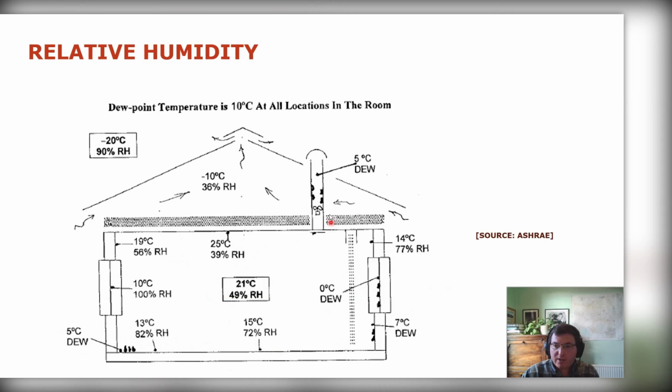Another interesting point shown here is that, let's say we have an extractor fan that takes this warm, moist air and pumps it out. Now, if inside this duct itself, it cools down because the loft that it goes through is cold, and the walls of it lower down to say 5 degrees C, again, it's a dew point, and at that point we start to get condensation inside the duct, and then we get water and maybe corrosion and a growth of algae and stuff like that. So again, that's where you have to be careful, because sometimes people think, well, it's perfectly fine, it's 50% relative humidity, I'm just throwing it out through a duct. Depending on its length and its shape, you may risk that you'll have condensation within it.